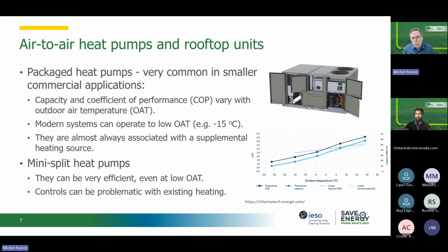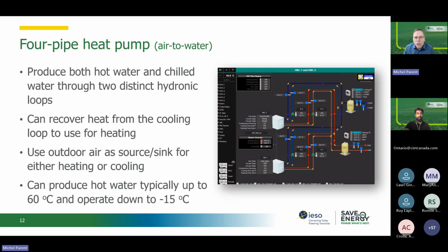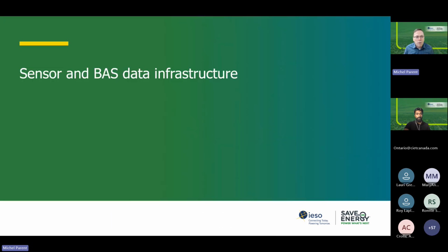That's why, in general, you see the distinction between COP and performance, because of those non-steady state conditions you have in real life compared to manufacturers' lab testing. So you've got to be very careful about manufacturers' data. They're always under steady state conditions. Just like a boiler will lose a lot of efficiency due to short cycling, heat pumps, depending on how you control them, will lose efficiency because they are always more efficient under steady state, which is often not achieved for long periods of time in actual buildings.